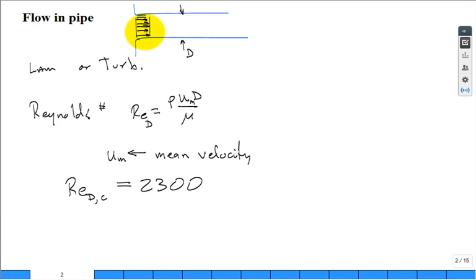It's going to be uniform velocity over the entrance region to the pipe. And then the presence of the wall is felt, and just like we have a growth of a boundary layer, we're having the growth of the influence of the wall into the core. And after a while, down the length of the pipe, it becomes what we call fully developed.